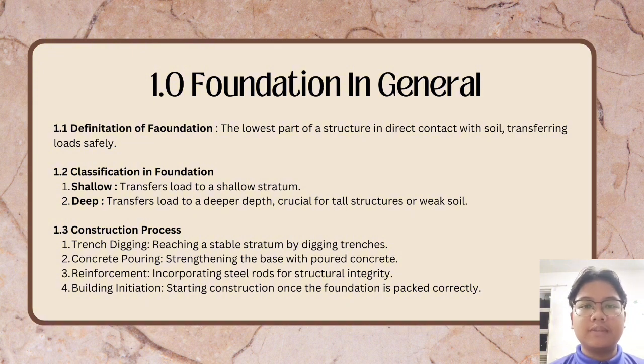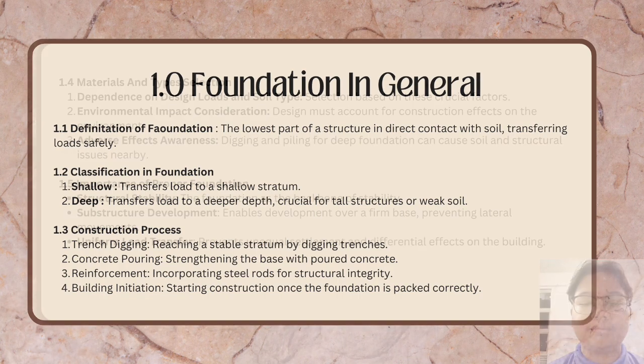1.3 Construction process. First is trench digging, reaching a stable stratum by digging trenches. Second, concrete pouring, stabilizing the base with the poured concrete. Third is reinforcement, incorporating steel rods for structural integrity. Last but not least is building initiation, starting construction once the foundation is packed correctly.